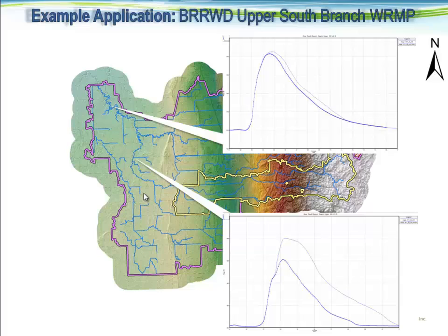And as you move downstream and you accumulate more area, so that basically the percent of area you're controlling is constantly reducing, you see less benefit as you move further downstream, which is illustrated in the top hydrograph, where we are still taking volume off of the peak, but it's substantially less percent volume out of the existing versus the proposed hydrograph at that location.